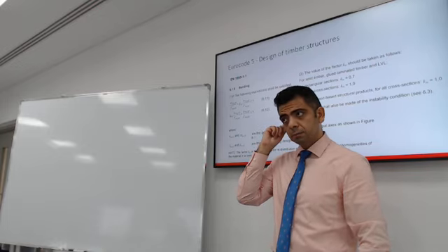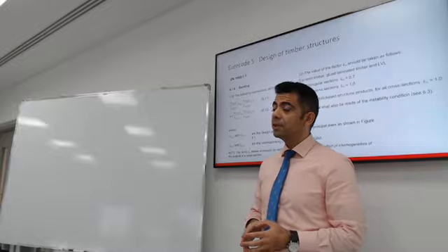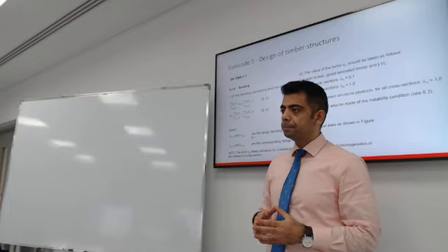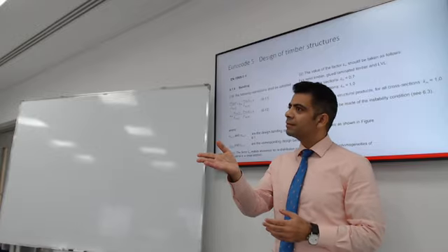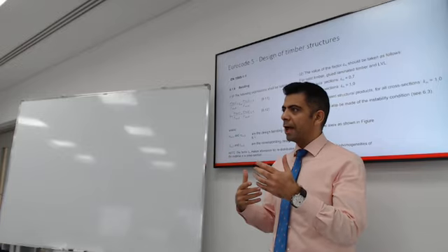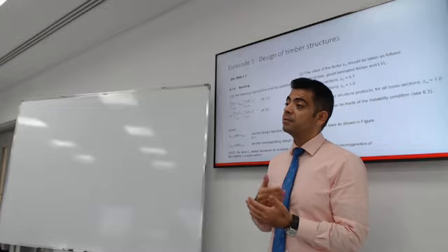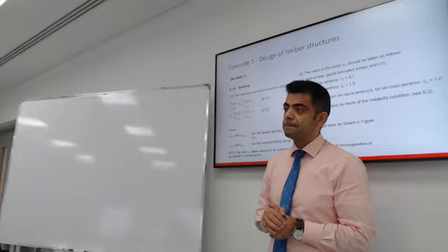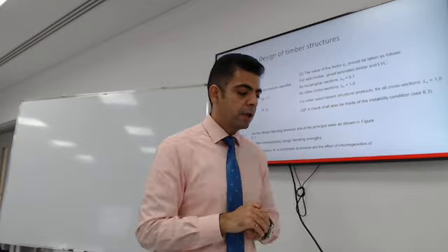It's just that, for example, we said we can't use it for foundations because of water. Yes, it's not very good for foundations. Rain, snow, winter and summer temperatures, termites, insects. Yes, biological threats could actually deteriorate wood, and that's why it needs to be preserved, and sometimes the chemical treatment for wood will reduce its capacity. So there are a few things that go into